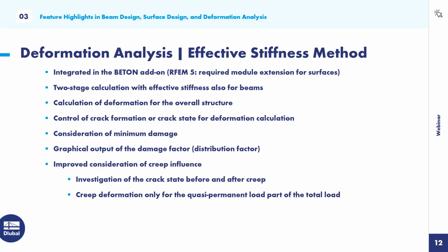It is that the creep deformation will be only calculated for the quasi-permanent load part of the total load. So only the quasi-permanent load part gets then the creep influence and will be then additionally considered with the additional short-term deflection from the higher load level.